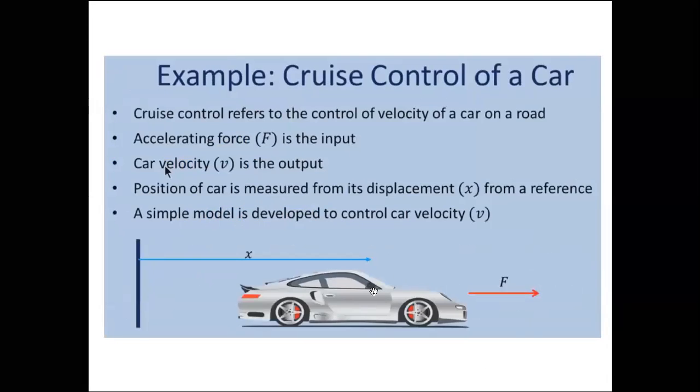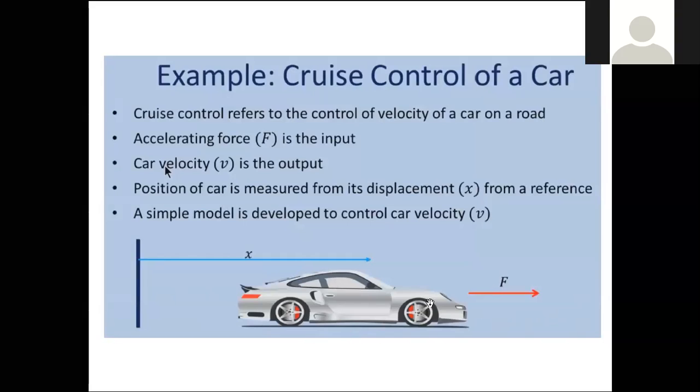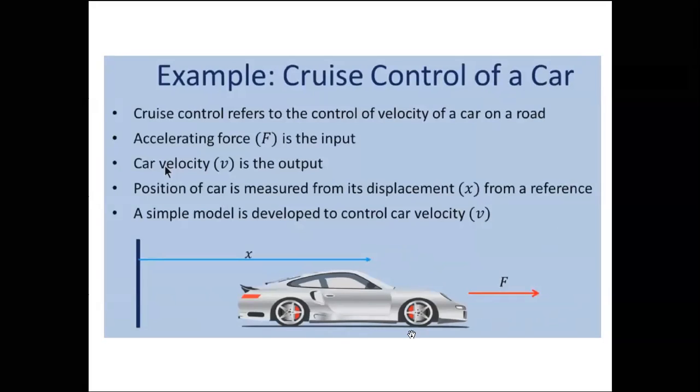If you observe the car here, it is moving along a line. We define this variant of motion of the mechanical system as translational motion. For translational motion, when you apply some force, because of the mass of that object, it will obviously resist. So first we identify the elements in this moving car. What are the three elements in a mechanical system in translational motion? Mass, spring and damping.